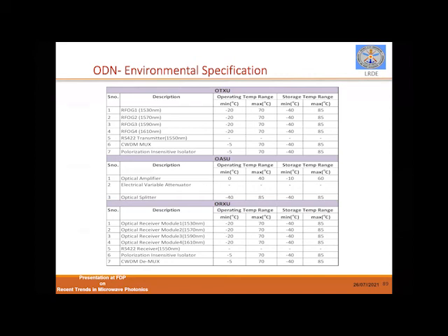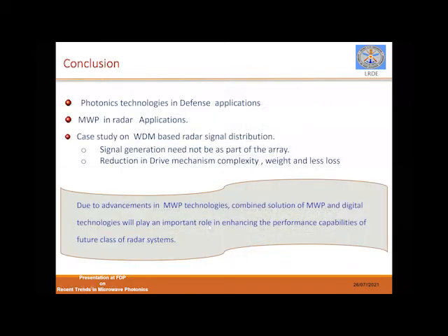So I wanted to tell you that in this case, we found that the optical amplifier did not have enough temperature range, and we had to make a separate outer enclosure where the ambient temperature will remain the same. With that, we could maintain the ambient temperature at a fixed value, and we could always meet all the required specifications.